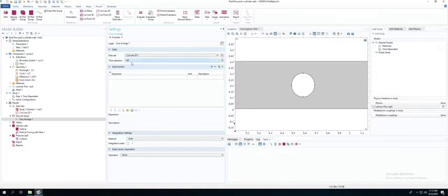You could change the name and so forth. Under the expressions, I'm going to type in U, because I'm going to be taking the velocity measurement. If I tab over, you can see it fills in the units for me, because we're going to do meters per second, which looks like what we have this in. Comsol knows it's a velocity field.